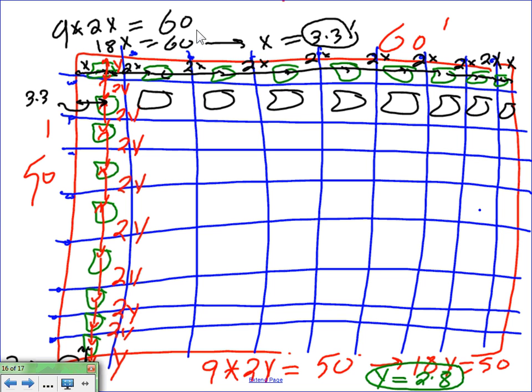Grounding electrode conductor. Can you splice the grounding electrode conductor that's going to the ground rod? Generally speaking, no. The grounding electrode conductor and the bonding conductors, the system bonding jumpers, we don't splice them. If you splice them, though, it has to be irreversible, meaning I can't go unscrew it. So remember one thing, the grounding electrode conductor must not be spliced. That's the general rule. The exception: if you splice it, then it has to be irreversible.